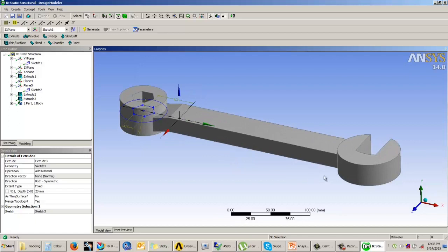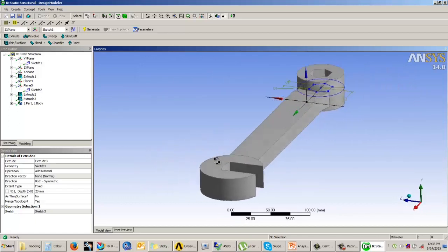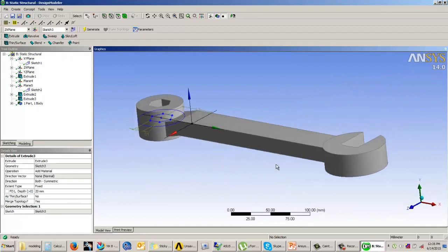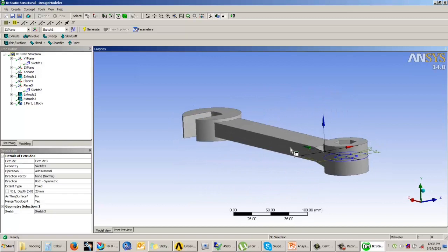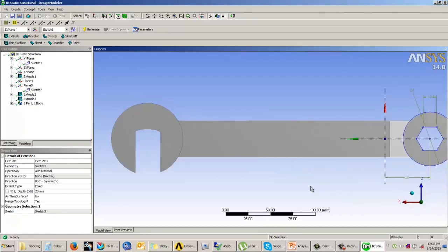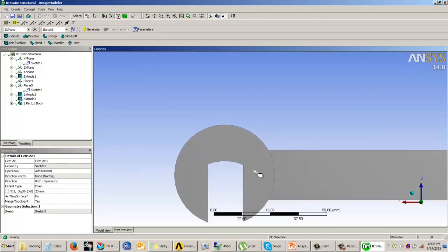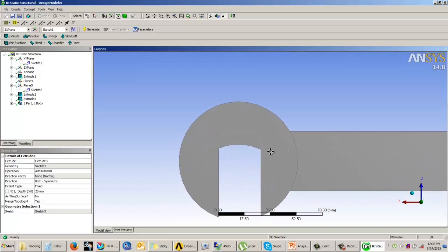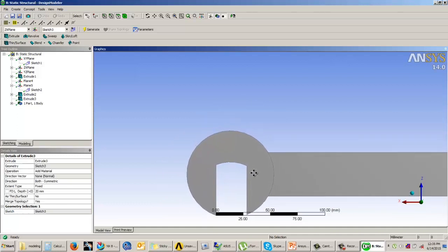We can add fillets over here, but we will see how to add fillets and chamfers in the coming chapters. Here you have just understood how to add the basic sketches and base features like extrude. Now we will see how to use the ruler. Now if I want to measure this distance, I can use the ruler to understand what will be the gap between them.